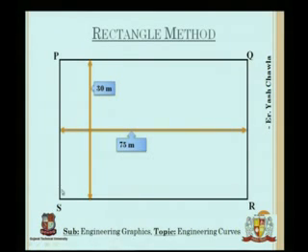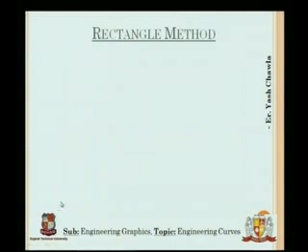But for constructing a parabola, this would be the initial point and this would be the final point. So the rectangle would be extended 1 meter beyond, but I just wanted to show how the rectangle method is applied in this particular figure. That's why I did not take 31 meters instead of 30 meters, but actually the rectangle that you have to draw is 31 meters, and then start the parabola from 1 meter above, or say 1 unit above, from whatever you are taking.